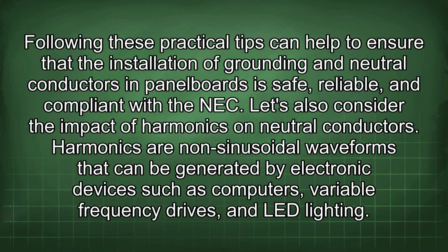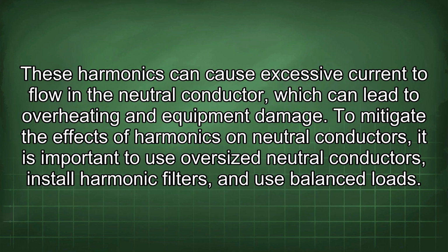Following these practical tips can help to ensure that the installation of grounding and neutral conductors in panel boards is safe, reliable, and compliant with the NEC. Let's also consider the impact of harmonics on neutral conductors. Harmonics are non-sinusoidal waveforms that can be generated by electronic devices such as computers, variable frequency drives, and LED lighting. These harmonics can cause excessive current to flow in the neutral conductor, which can lead to overheating and equipment damage.